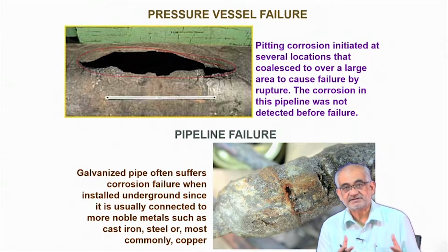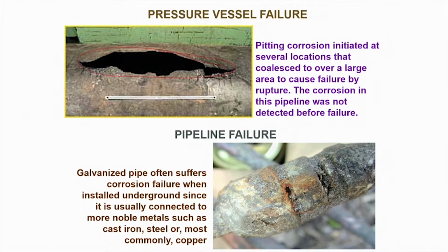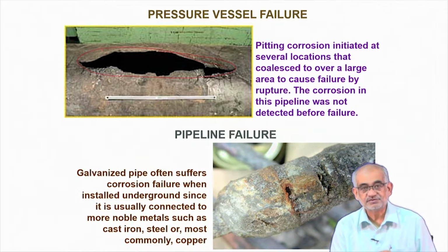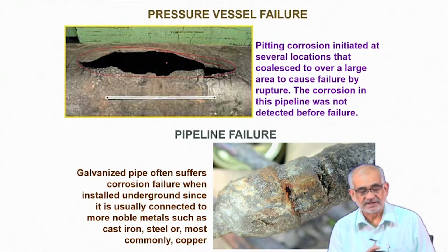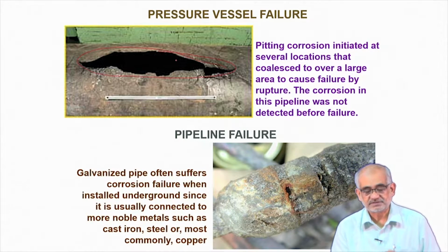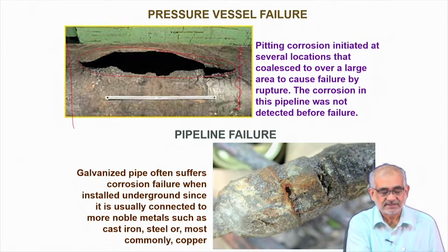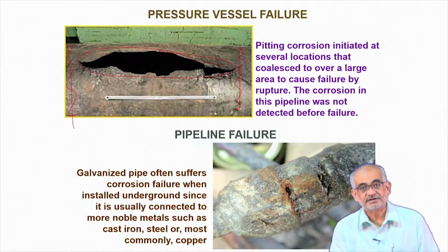So for power generation, you need very high pressure of vapor. So you boil water in the boiler, and then you allow the steam to escape, and that steam escapes through tubes called the pressure vessel tubes, and those tubes are exposed to such high temperature and pressure conditions before they interact with the turbine. So these ruptures are very common in the pressure vessel tubes, and when such rupture happens, then either you chop off from these two ends and then bring in another piece of tube and join by welding at these two spots. Then these welding joints become another possibility of future failure region. So one has to be careful about them.